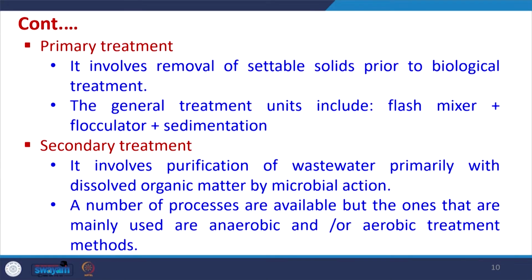Then primary treatment involves removal of settleable solids prior to biological treatment, and the general treatment units in this include flash mixer, flocculator, and sedimentation basin. So, all these coagulation and flocculation steps come into the primary treatment.